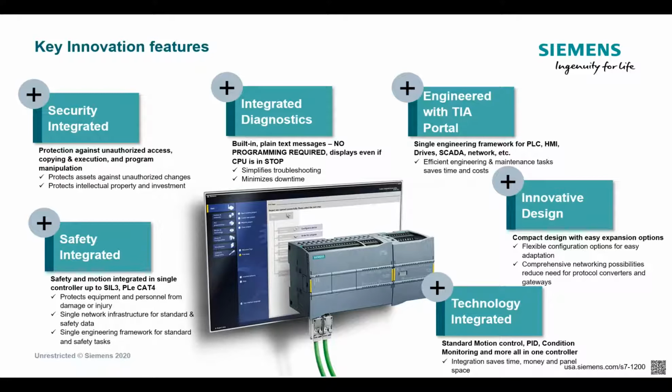Integrated diagnostics is a pretty important feature when it comes to programming inside of TIA Portal. With a lot of other manufacturers, you actually have to go in and find all of your diagnostics for your different I/O cards, for your processor, and actually manually program alarms. But with Siemens, with the 1200 and with a basic panel, literally you can check a box and get all kinds of integrated diagnostics on the I/O, on communication, hardware, and it's all just checking a box.